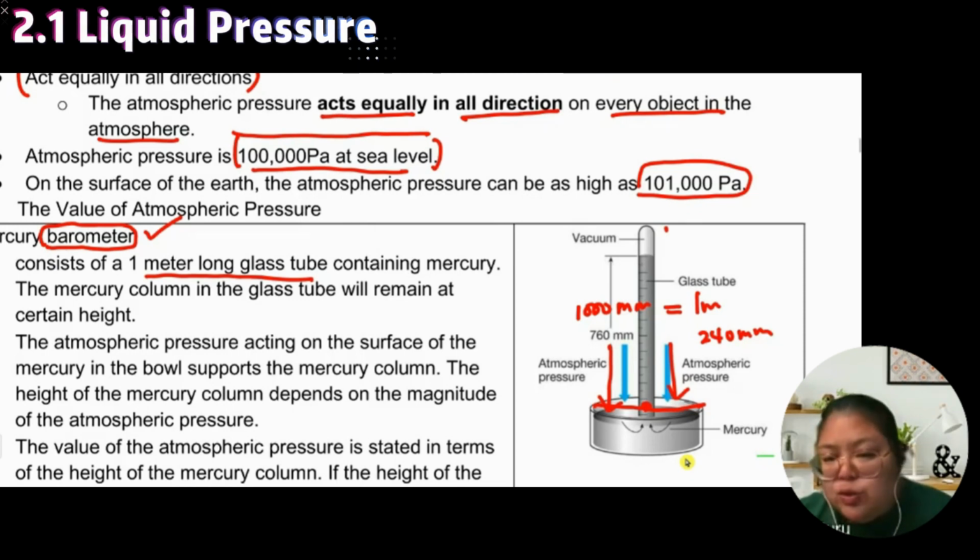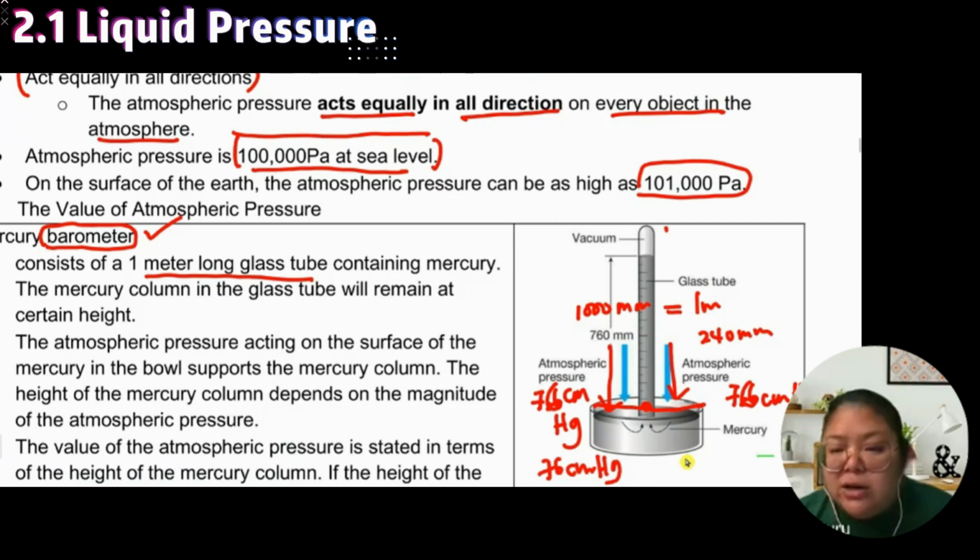So we got 3 levels. 左边 atmospheric 压，右边也是 atmospheric 压，中间呢关注了的，但是 same level same pressure 嘛。atmospheric 是 76 cm mercury，左边也是 76 cm，中间那个肯定也是 76 cm mercury 嘛，same level same pressure 嘛。Understood? If I say this side also 76 cm mercury, this one height how many? 肯定是 76 cm. This one unit 76 cm mercury. That's one of the units for the pressure when we use mercury.